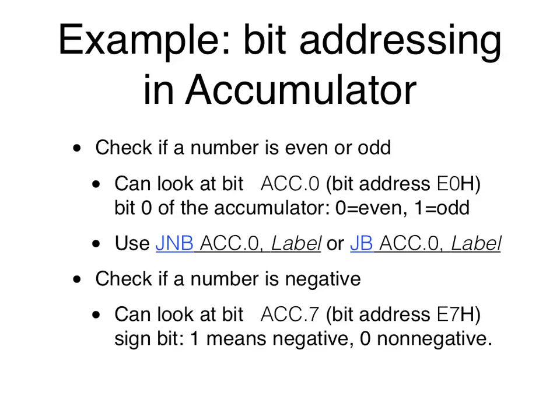Okay. So now, how is that useful? Well, if you can check the individual bit, that can tell you quite a bit about the result, because the accumulator stores the result of a computation, right? So if you look at ACC.7, that's actually a sign bit. So it allows you to determine if something is negative or not, right?